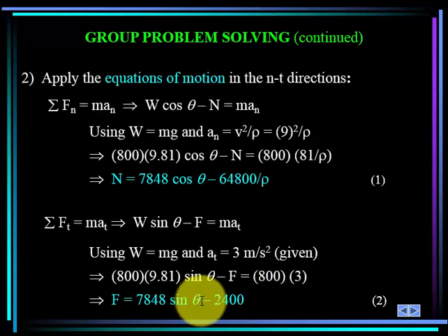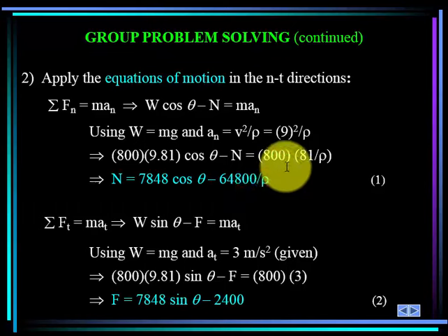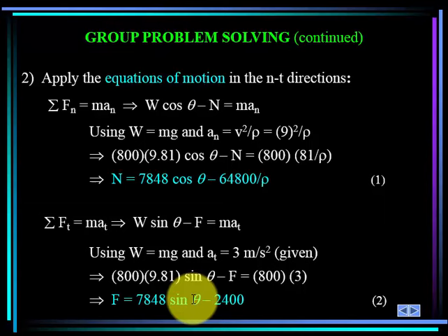Notice again that the angle theta, which is the angle of our slope, is unknown. We will have to find that. How will we find that? And how will we find the radius of curvature? Radius of curvature, you know, we have a big ugly equation. The angle of the slope is very much like a couple of the quiz problems that we just did, where we know the path. We can take the derivative of the path equation to get the slope value, and we can do inverse tangent of the slope to get the slope angle.